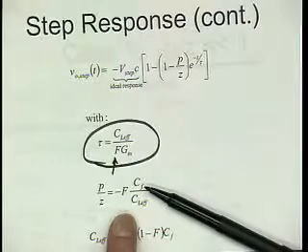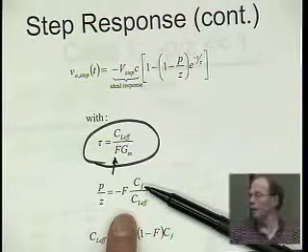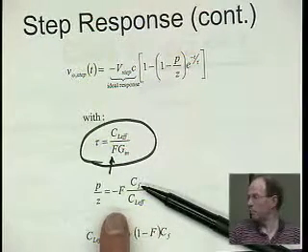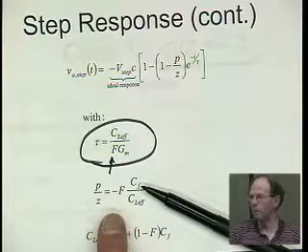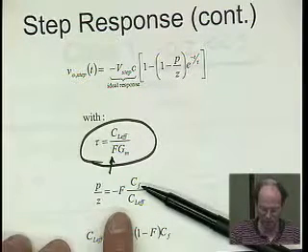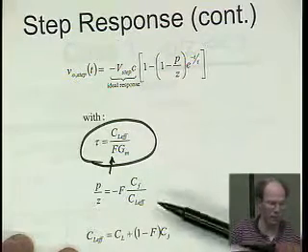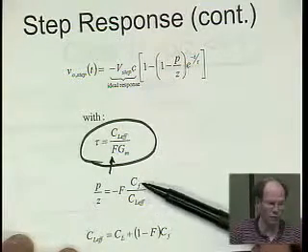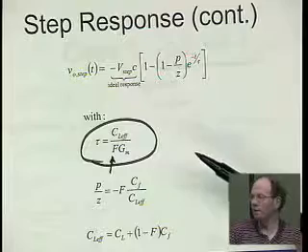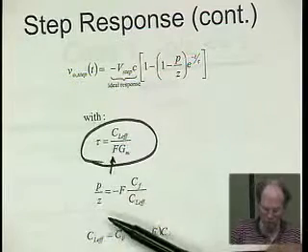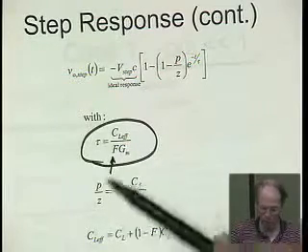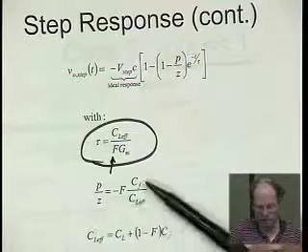If we want a gain of 4, then we are going to have F being less than 0.25, probably a bit less. We have 1/6 in example. And the other thing is that this ratio, well, often the load capacitor, of course, is larger than the feedback capacitor, and so that is not unrealistic.